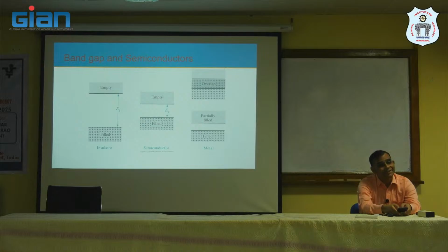1100 nanometers, so 1.1 micrometer. Actually, while you were doing this calculation, I found a web page which does photon energy calculation. Did you find that as well? You just enter the energy and it gives you the photon wavelength. Were you able to find that? Okay, good. So silicon could do up to 1.1 microns.